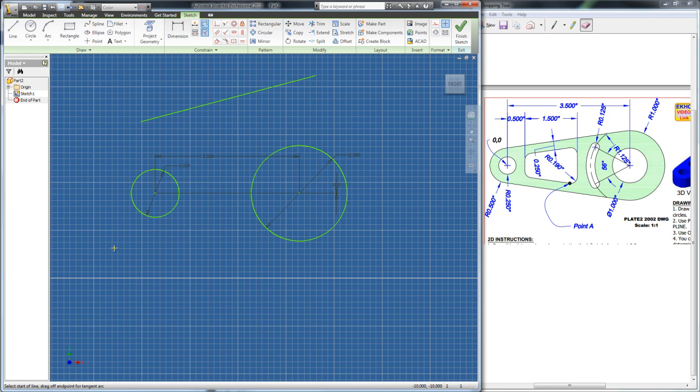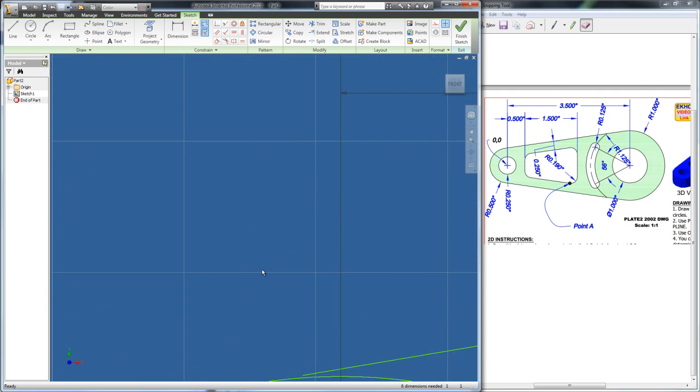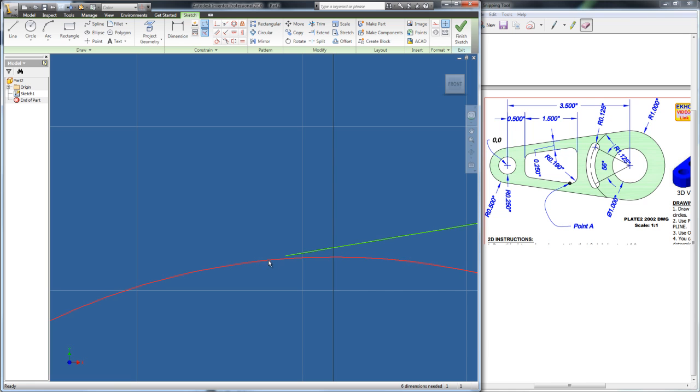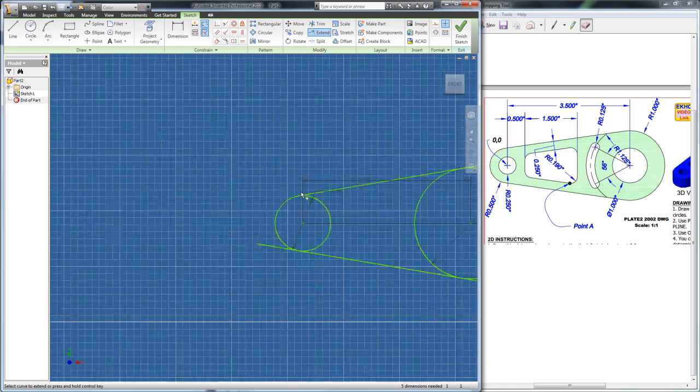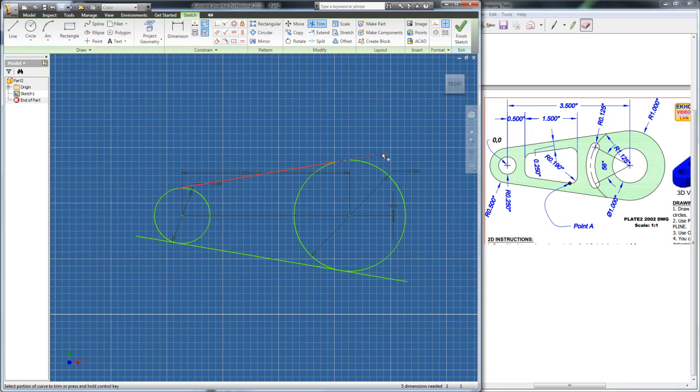So I'm drawing lines, L, or click the line, click, and then escape. So now let's make them tangent. So we use our tangent constraint. Whoops, that's parallel. So tangent constraint, escape, spacebar to do it again for this line. And this, we're going to want to extend it to hit the circle. So hit extend, and the rest of them we're going to want to trim off.